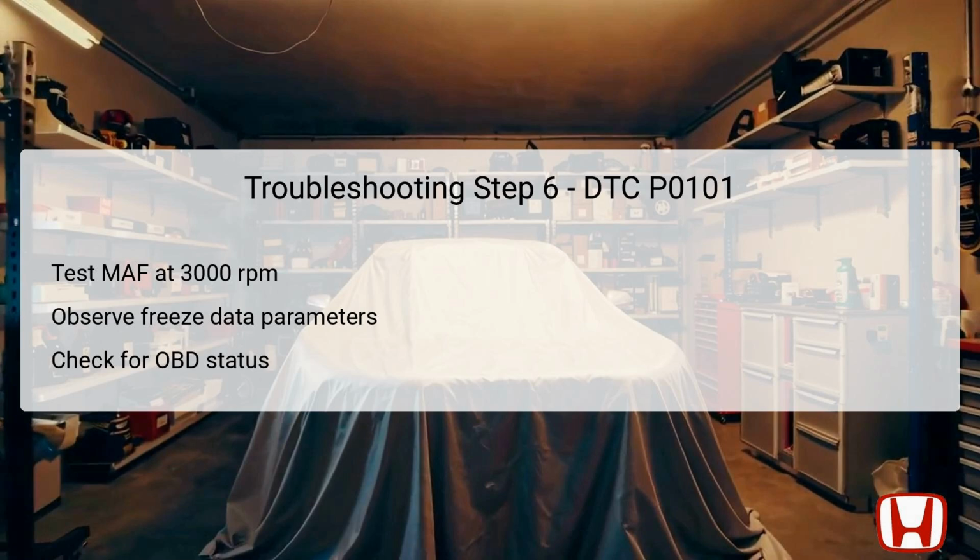After the test drive, the OBD status must be checked using the HDS to determine if DTC P0101 is still present. If the system records an error, it becomes necessary to replace either the MAF sensor or the IAT sensor and verify that the repair resolves the issue. Accurate monitoring during this phase is important as it ensures that the MAF is performing as expected under various driving conditions.